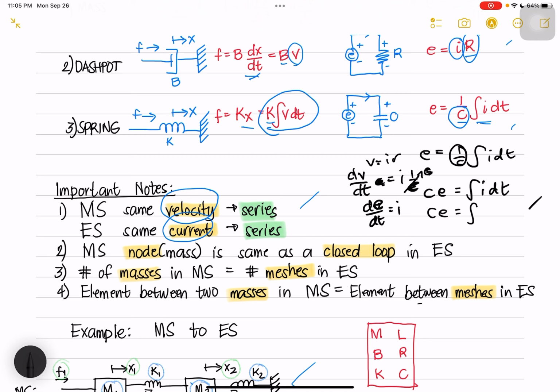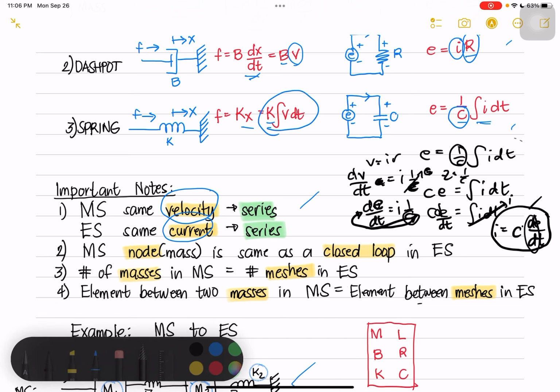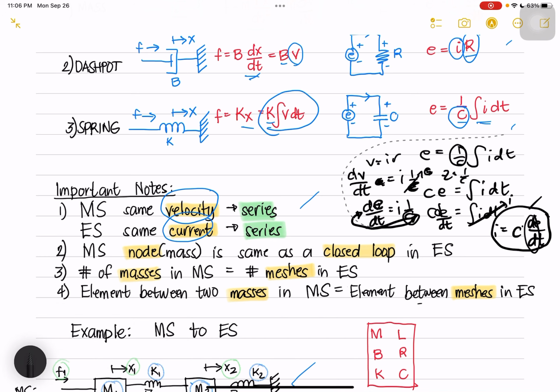I times 1 over C, and Z is equal to I times 1 over C. So, if we move this here, it becomes C, the derivative of voltage, over I dt, which becomes just I. So, I is equal to C dE over dt. What we are doing is matching the format of the mechanical system. The format meaning whether it is a first derivative, an integral, or has no derivative or integral.